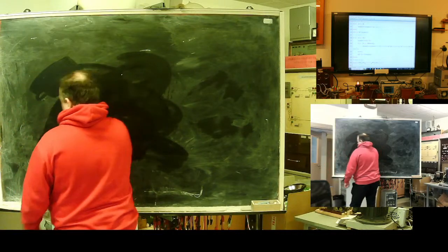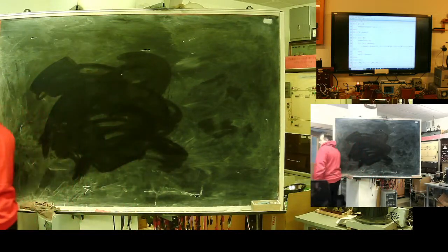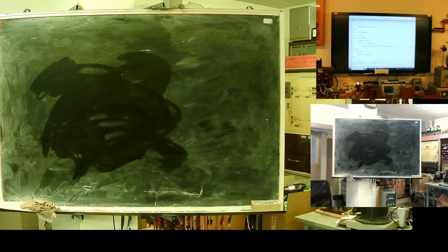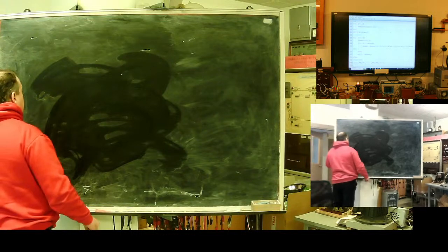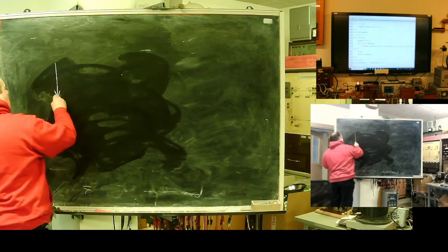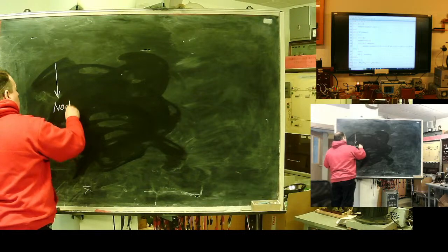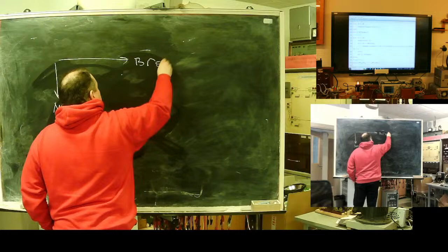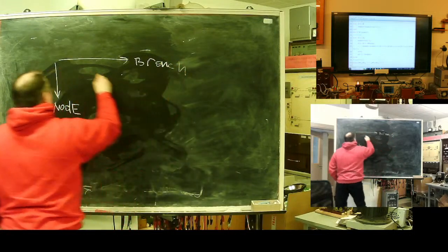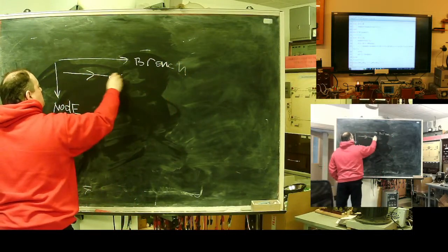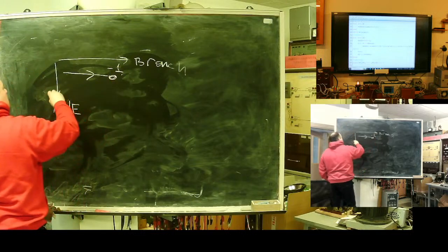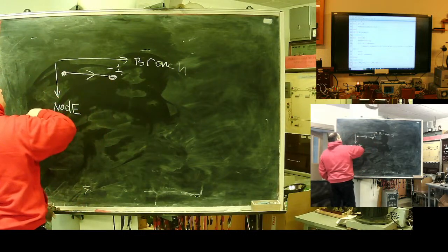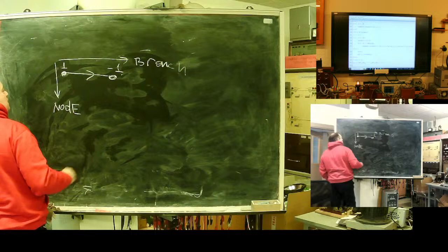Another easy thing is a matrix of incidence. I need network topology, and a matrix of incidence of node and branch. If a branch flows into a node, I should write minus 1. If a branch flows out of a node, I'm writing 1.